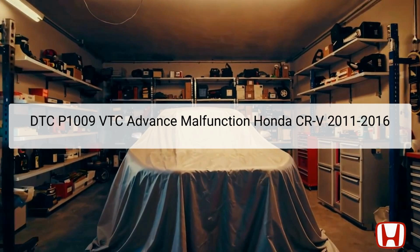DTC P1009 indicates a VTC, Variable Timing Control Advanced Malfunction, in Honda CR-V models from 2011 to 2016. This code signifies that the engine's timing system, which allows the engine to adapt its timing for optimal performance and efficiency, is malfunctioning. The VTC system is responsible for adjusting the camshaft timing based on engine speed and load. A malfunction can lead to poor engine performance or increased emissions.